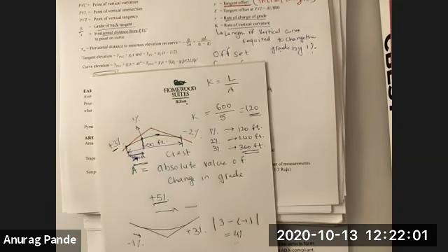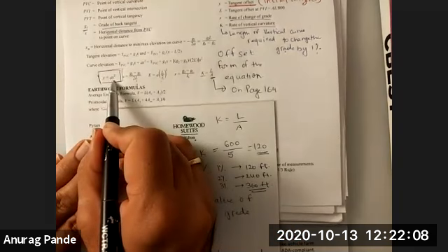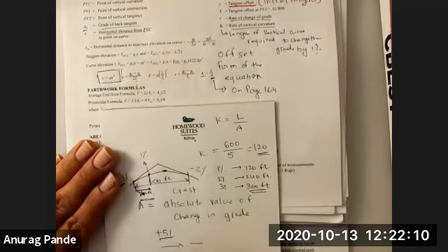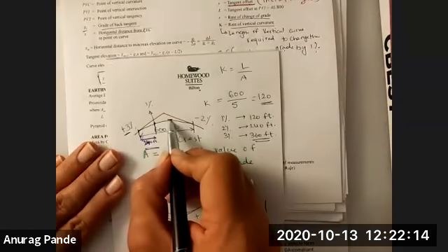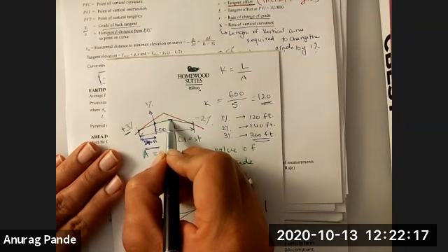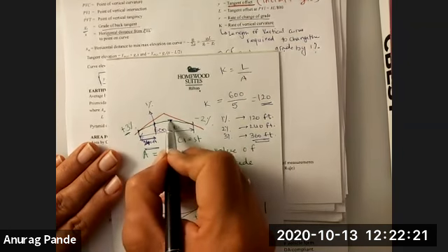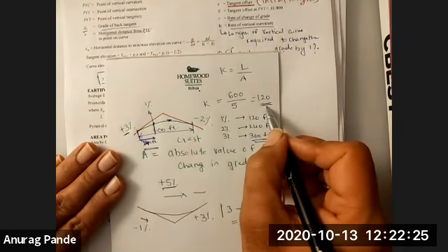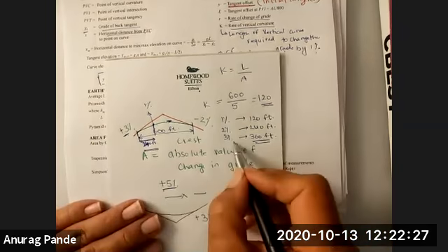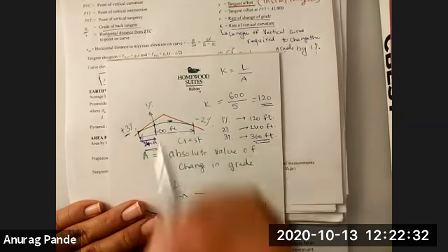And these types of examples are very important because if you do this calculation using the offset equation, it'll take you a lot of time to solve it. But if you use the K value, you can arrive at the point where the curve is flat very, very quickly by figuring out what your initial grade is. To go to 0, how much change would you need? And then if you know the K value, you can quickly derive the length that you require to go from whatever grade the initial was, and then you could do that same thing.